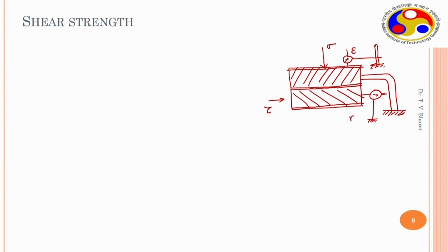When you have this kind of setup, we often measure the dilatancy effect by plotting the normal strain, or the vertical displacement, against shear strain. Positive is compression and negative is dilation, or swell, or increase in the volume. So when the volume decreases, that is positive, and when volume increases, that is dilatancy, negative.